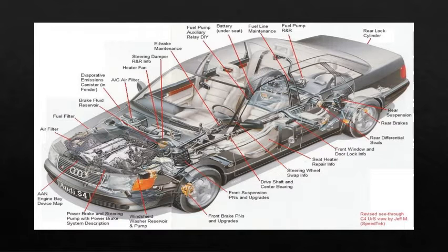With the advent of the chip and its continuous refinement, it is easy to equip a car with a small central computer powerful enough to allow complete automation of the car functions. The microprocessor for a fuel injection system, for instance, needs to have information on engine speed and load setting, air temperature and air density, if it is to provide the correct mixture under all conditions, and even this may not be enough. Each of these quantities requires a separate sensor, each of which must be interfaced with the computer.